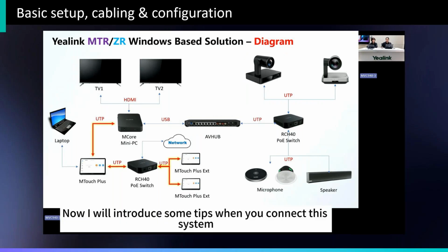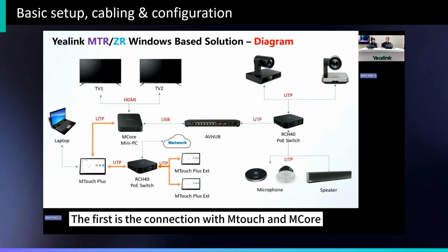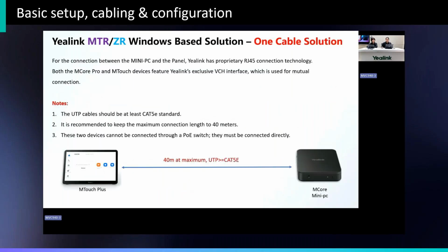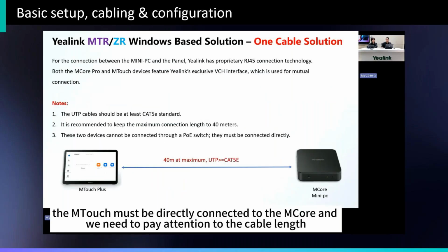Now I will introduce some tips when you connect this system. The first is the connection with M-Touch and M-Core. As I mentioned earlier, the M-Touch must be directly connected to the M-Core, and we need to pay attention to the cable length.